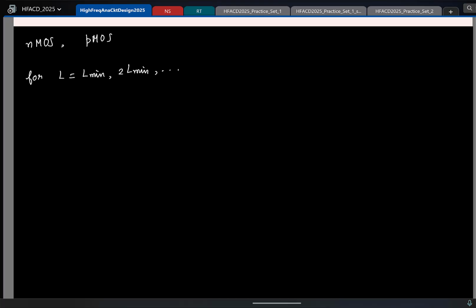So that is the first. What is the second parameter I have to sweep? VGS. So the second for loop, again this is just pseudocode I'm writing, you sweep VGS from 0 to whatever maximum value you have. And then what parameters should I store? All the width independent parameters.